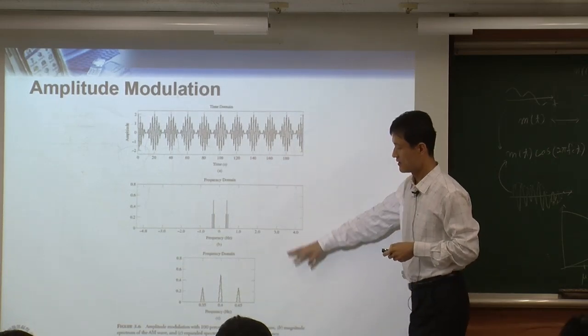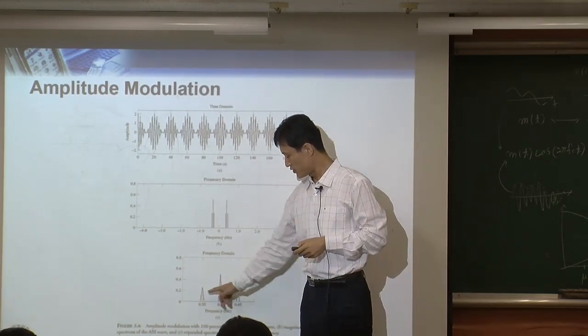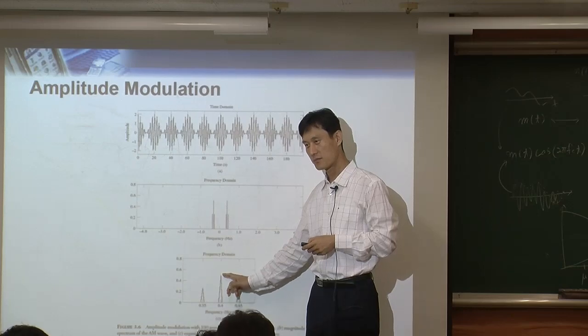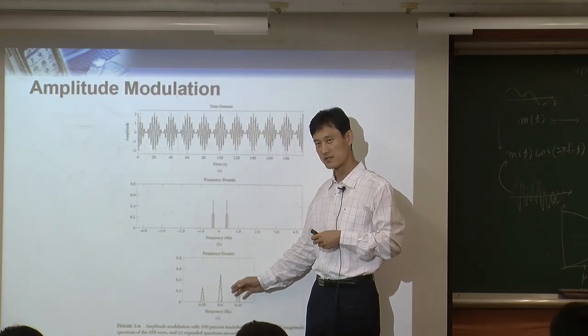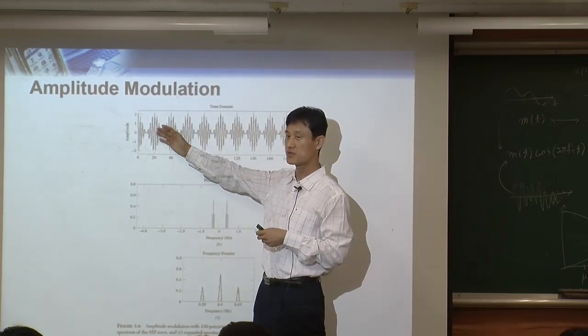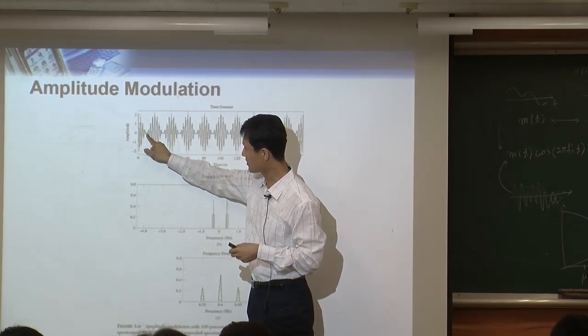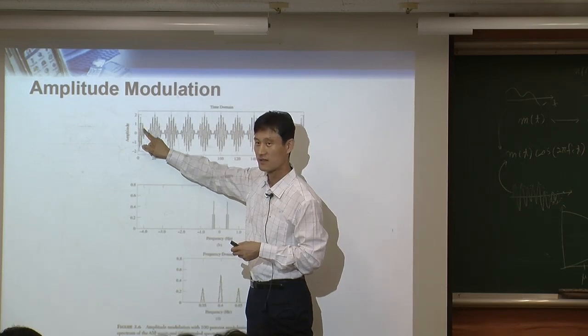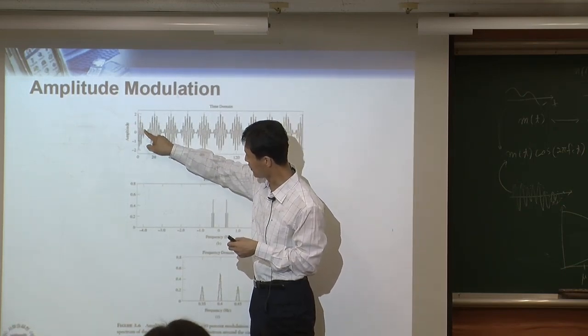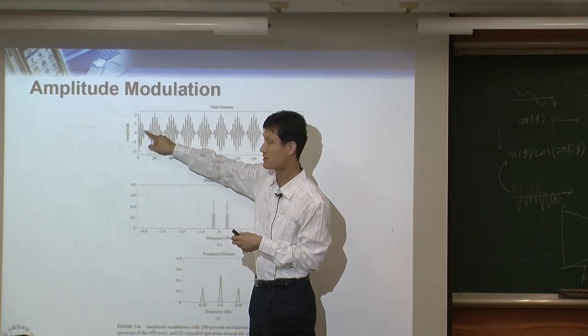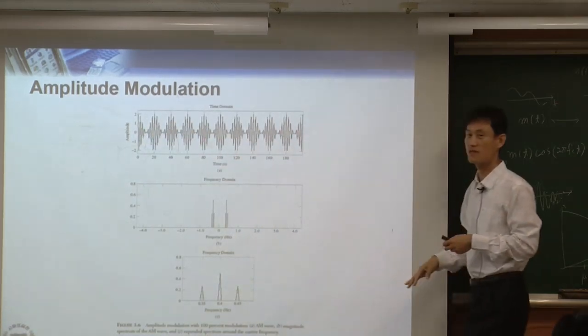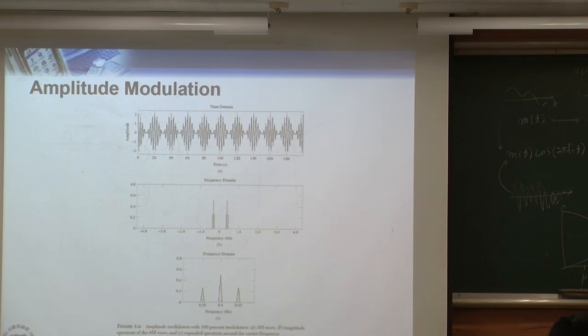In this case, you still waste some energy, but better than the under modulation case. You can still use envelope detection because your signal, the lowest point, hits 0, but not negative, right? So it's very close, almost like 0. So you can still use envelope detection. Therefore, we can say that mu equal to 1 would probably be the best selection for you.